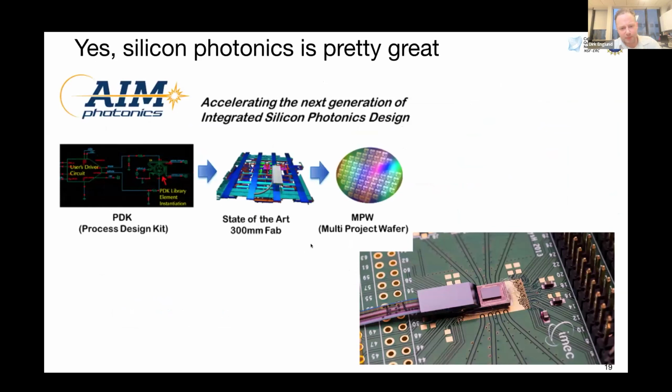But silicon is a particularly mature technology, to the point that increasingly telecom equipment, which runs your internet traffic, can actually be encoded and decoded by silicon waveguide devices. Here's an example of one of these devices. Here's your optical fiber entering through a grating coupler into a photonic circuit, which is located here. And here's an ASIC on top that does some of the control electronics for encoding and decoding, modulators for encoding, and transimpedance amplifiers for decoding steps of this so-called transceiver.